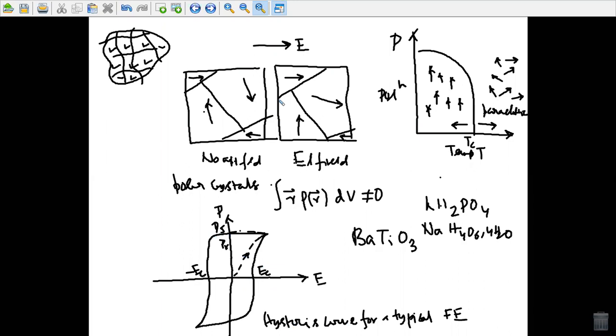Linear dielectrics, which are most of them, do not show significant hysteresis in an alternating electric field, but there is a structural requirement for ferroelectricity. There are a total of 32 different symmetry point groups, 21 of which do not possess a center of symmetry. Ferroelectrics are part of a small subgroup of these non-centrosymmetric crystals.